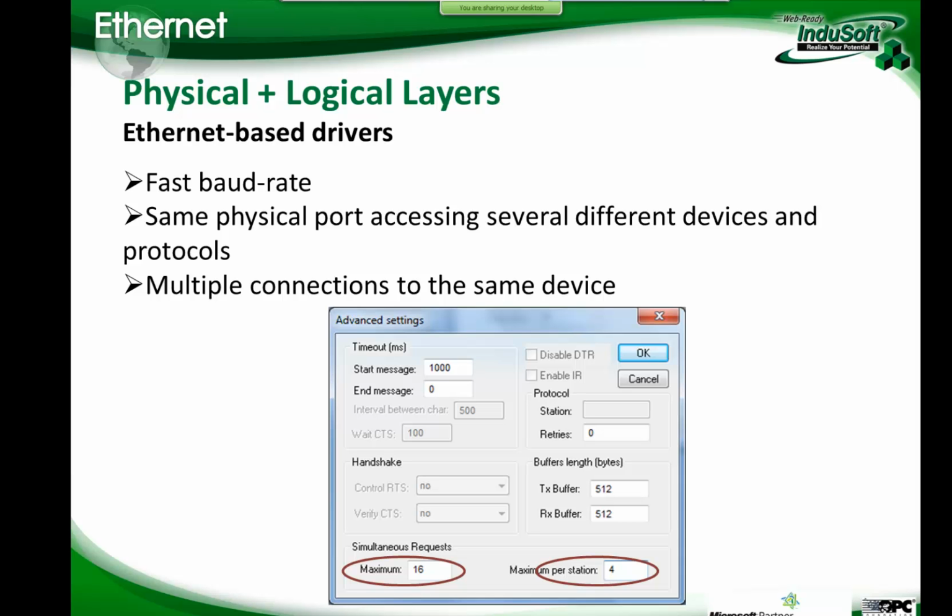And when I say new message, let's say I'm going to talk to Allen Bradley PLCs, the older PLC-5 and SLC family. I want to read the N7, I want to read the B3, I want to read the timer T4. For each one of these, up to 64 of those addresses, I'm going to prepare a message, send the message, and then wait for the reply. And not you, user, but we, the driver. So we read the N7. After that, we read the B3. After that, the inputs. Only after that, the timers.